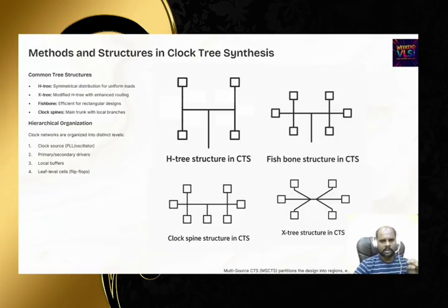What is the use case? It is designed for balanced clock distribution when sinks are spread diagonally across the quadrants of the chip, and useful in chips that need low clock skew and symmetric placement. These structures are good for better clock skew also. Advantage, you will see zero skew and highly symmetrical distribution, good for high frequency designs. Better delay balancing compared to fishbone or spine.